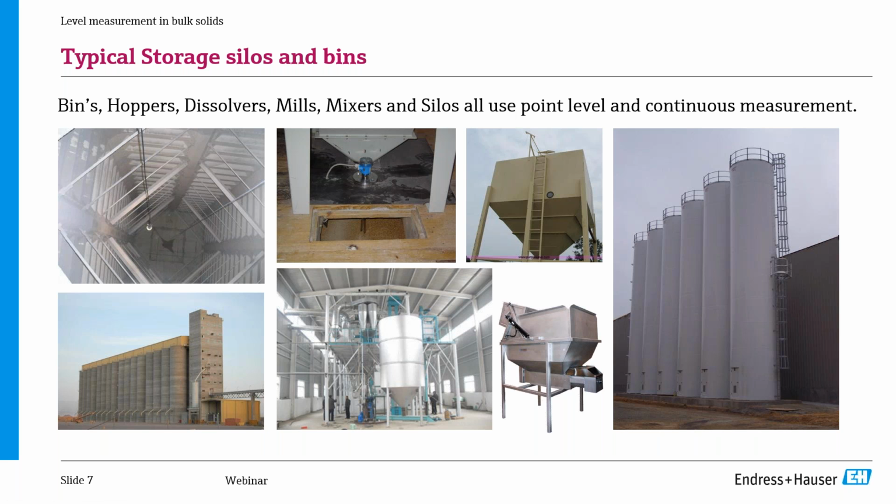Cool. So what do I need to consider to really optimize my inventory? The first step is to understand your storage conditions. For solids in particular, there are several different sizes, materials, and geometries of silos and bins. For each one of them, we need to identify the best type of control model, whether by using just a continuous measurement or just by controlling a minimum and maximum level.